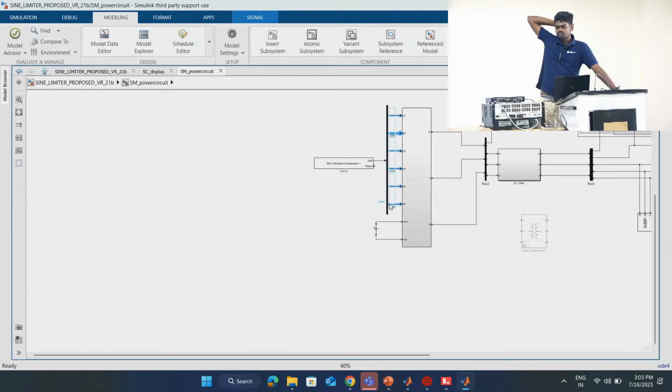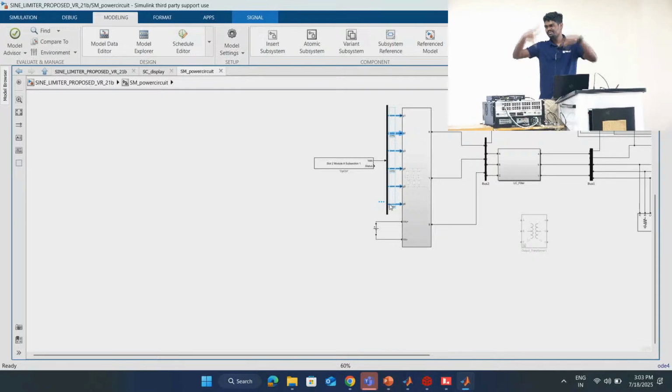So this is how you modify your simulation in such a way that it is ready to be tested in HIL. You go through the basic procedures I said, grouping into subsystems, changing the solver and all those things, and you configure analog outputs and digital inputs for this application. So now this is what the plant model is all about. Now I will go into the controller model.